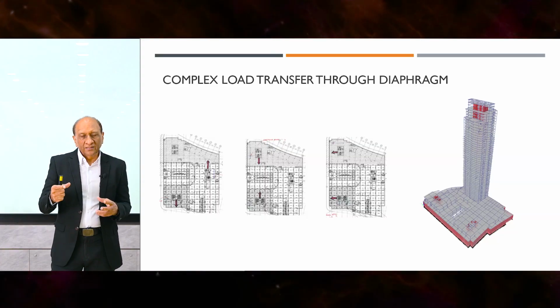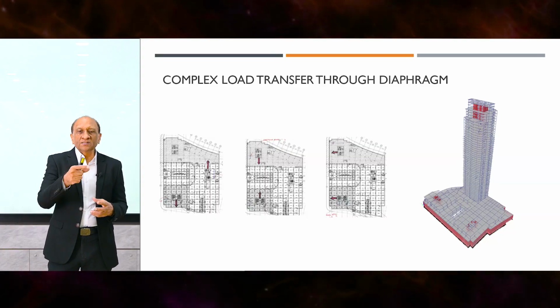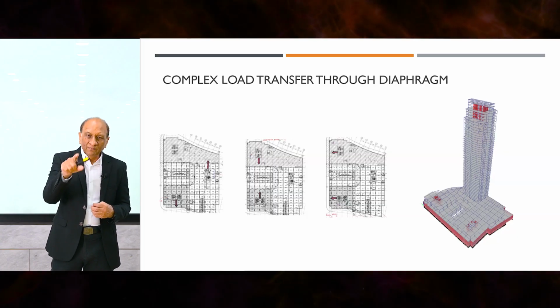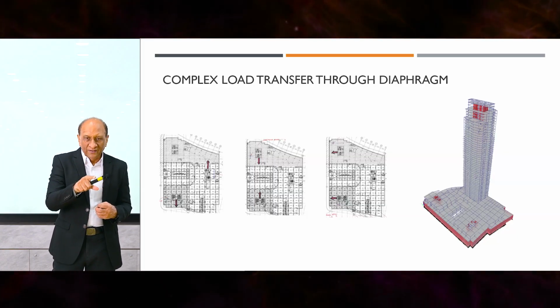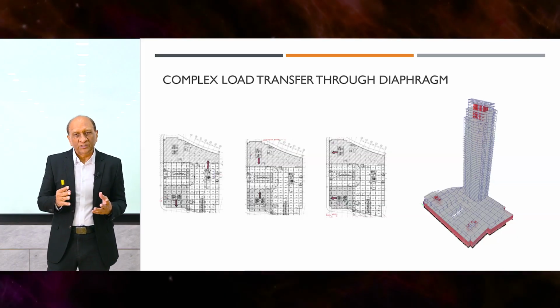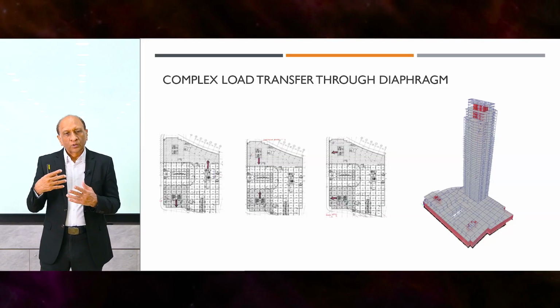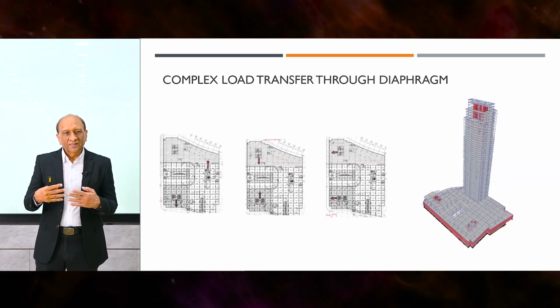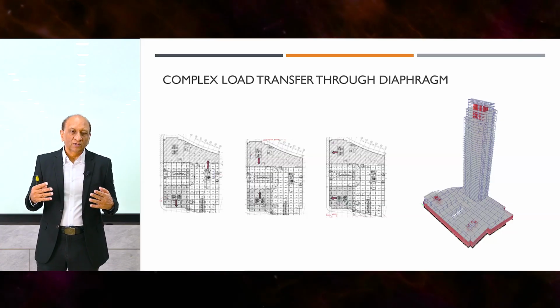So which means that intermediately, you have to consider many scenarios for the load transfer from the completed tower to the unfinished one. And then when all towers are complete, the towers may be moving in different directions because of their orientation. So at different time intervals and also in different earthquakes, they may be moving in different, opposite directions.